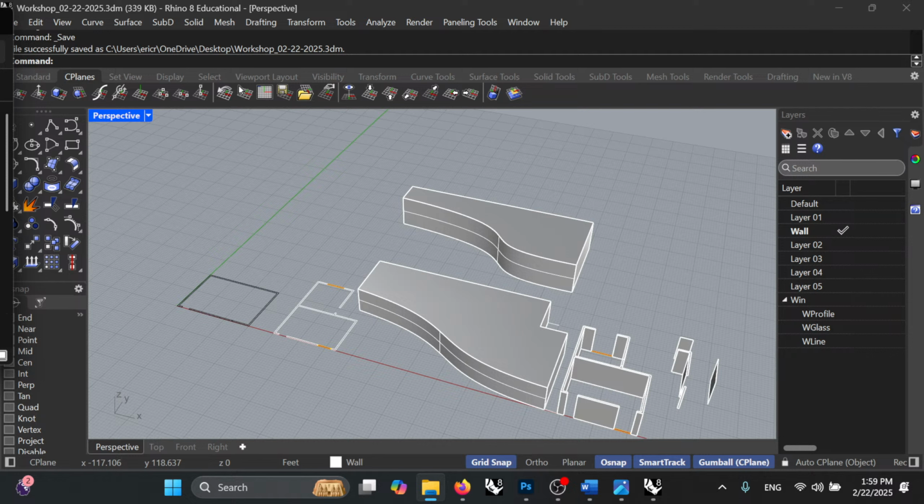When you do the cap with the windows, you cannot do the cap, because they're open. So you have to have a closed form and then make it solid. So cap is making it solid, meaning there is no opening to the outside, right? Then you can add the windows into that.